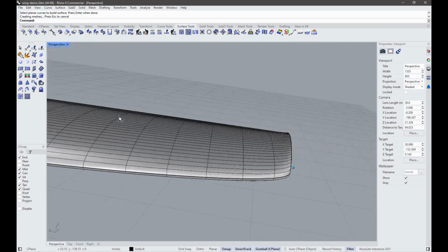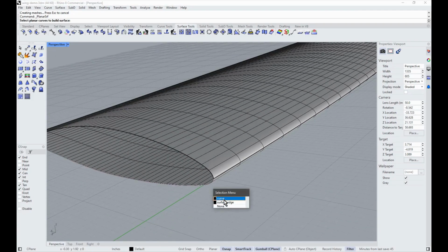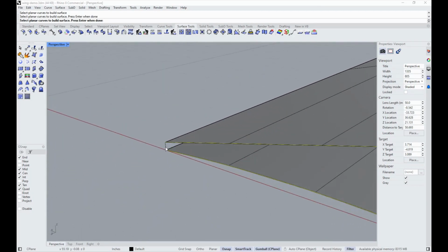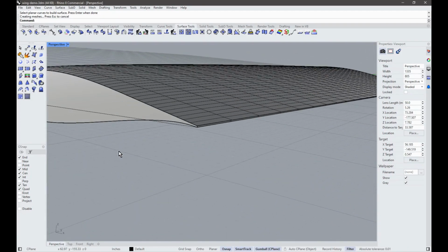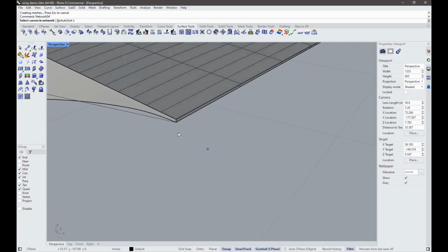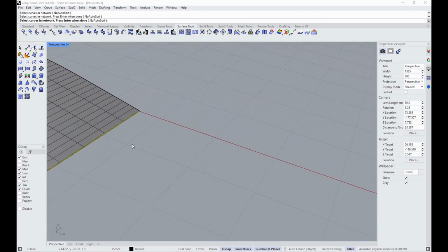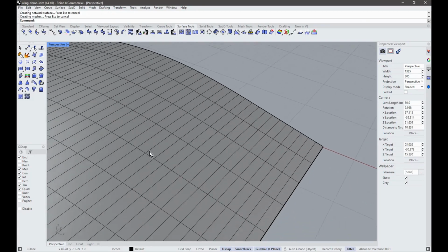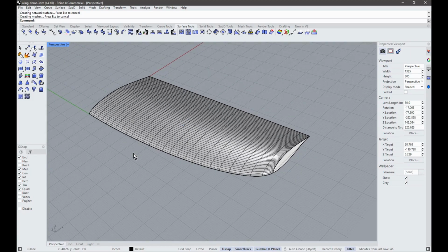So we made a tip. Make a root one. So a curve, curve, and the trailing edge. So that's all there. And we'll do the network surface on the trailing edge. Curve, curve, curve, zoom out, zoom in, curve. So yeah, there you go. So now everything is all surfaced and you should be able to do a create solid.